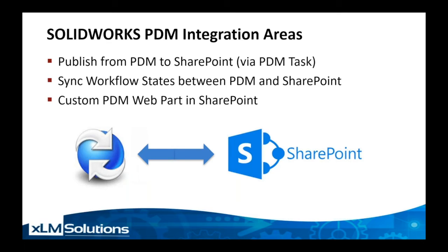By doing a status change in SharePoint, we can change the state in SolidWorks PDM. And then finally, we can build what's considered custom PDM web parts, which is kind of your own widget that would sit inside of SharePoint and do specific custom functionality from SharePoint interacting with SolidWorks PDM.